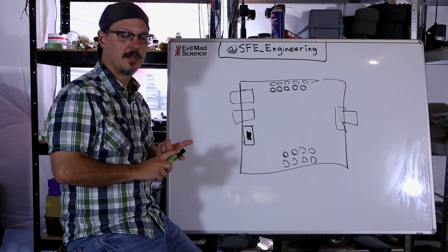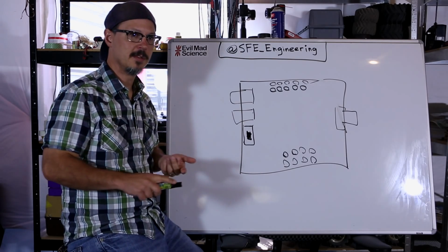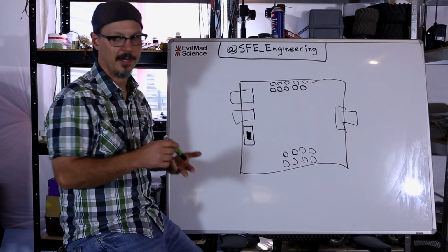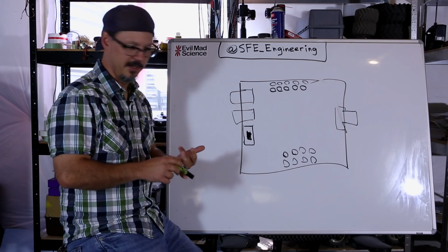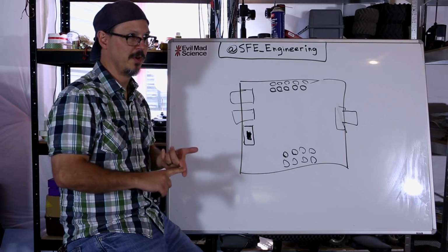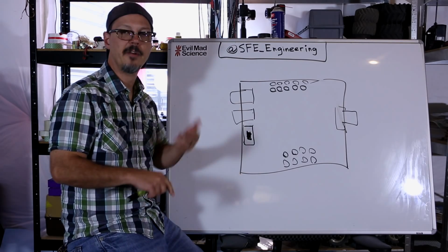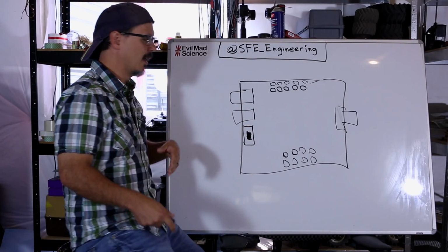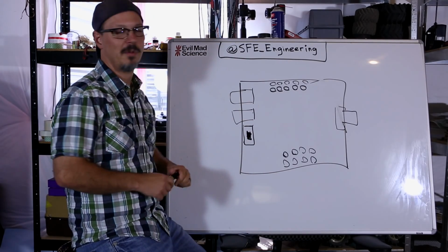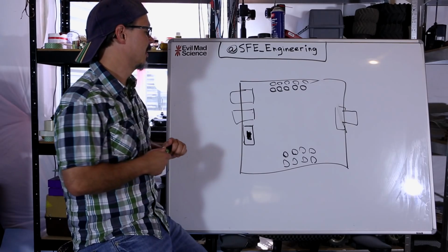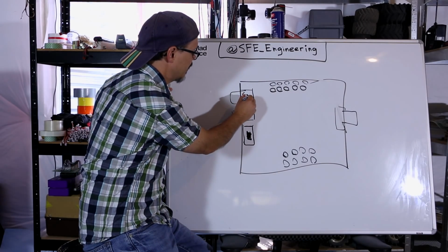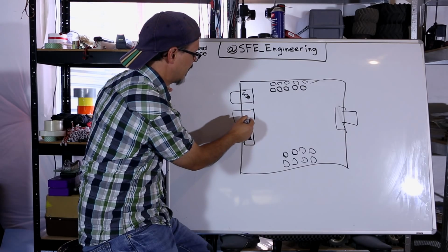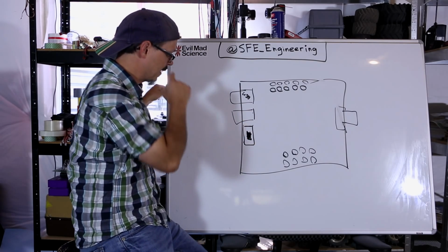The first section that I generally start with is the power supply, which is to say a regulator, a switch, maybe a fuse, decoupling caps, so like a 0.1 ceramic and probably a 10 or 100 tantalum, something like that. Those are just general parts that you might find in a regulator circuit. When I started this out, I identified this one as USB. I identified this one as like a barrel jack. So this is where the power is coming in.